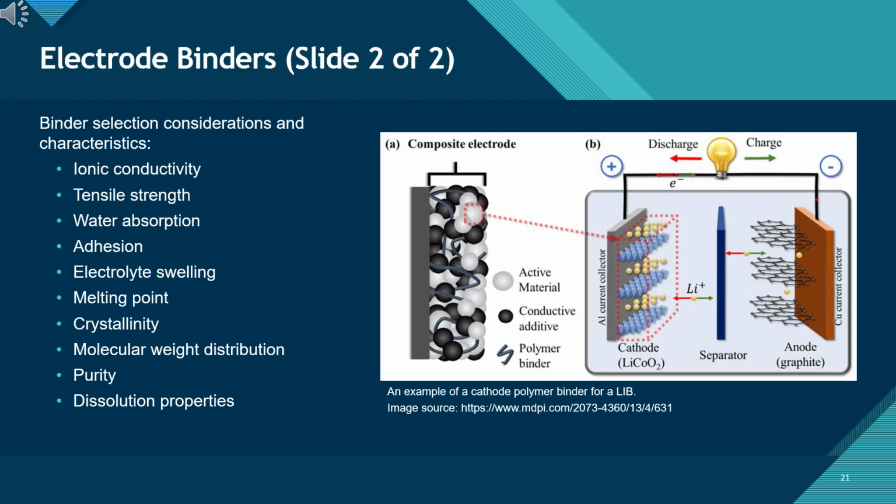The binder has a very tough job. It must be strong enough to hold the active materials to the foil, that is, adhesion. Still, it also has to survive sitting inside harsh chemical electrolytes for years without dissolving or puffing up too much. If you look at the diagram on the right, you can see how the binder acts like a web, physically connecting the active material particles and the conductive additives to the current collector. It must hold that structure together without blocking the flow of electricity.